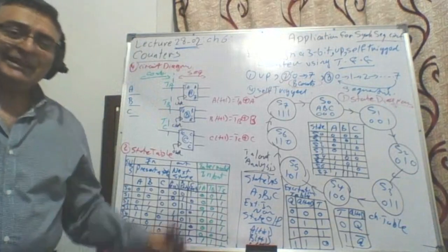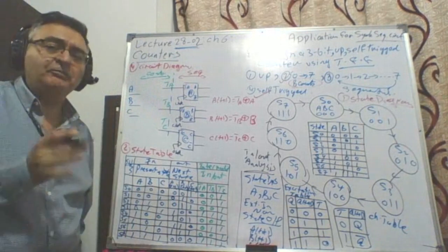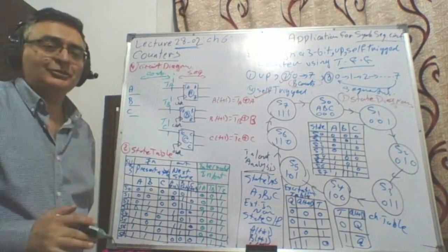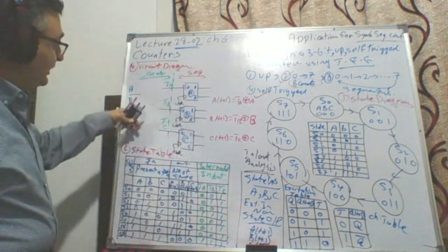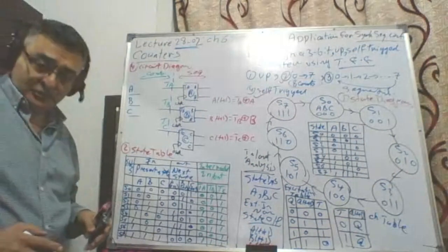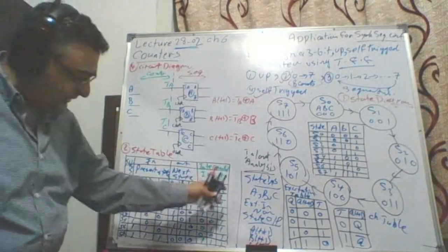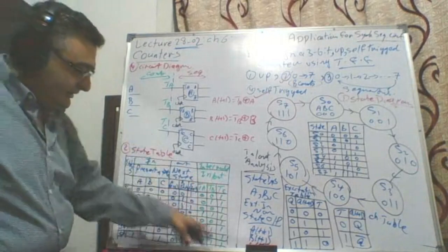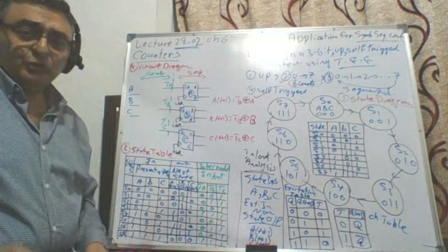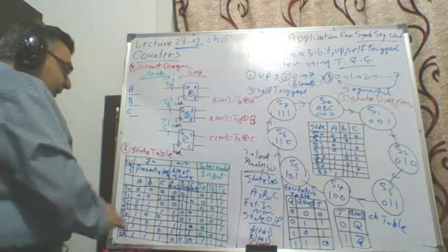That's why the T flip-flop is the preferred flip-flop to build counters. Why? Because the combinational circuit is very simple. Is it really simple? Yes, it is. Go and check. What should be the value of TC? TC is all ones. Do you really need a K-map?